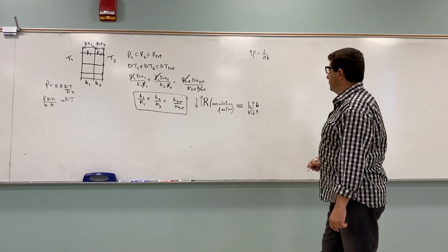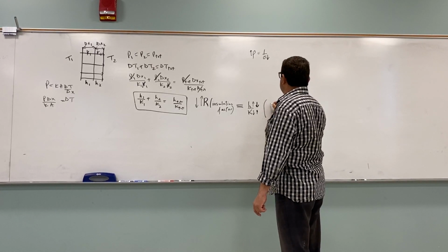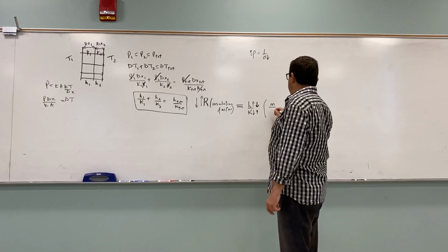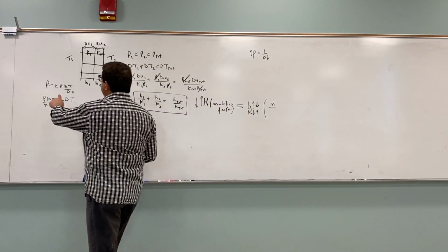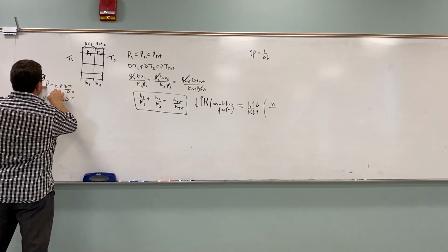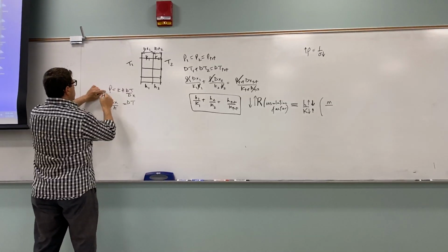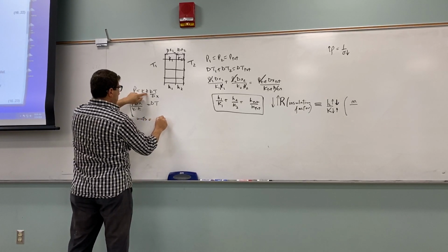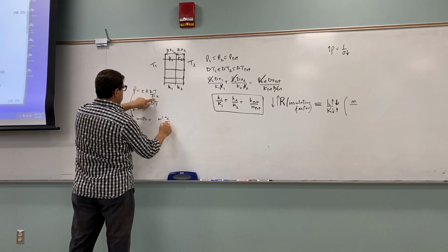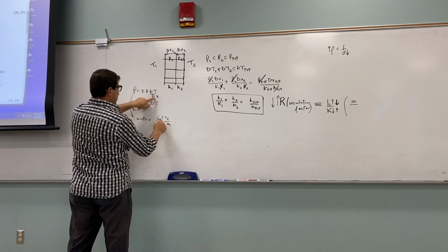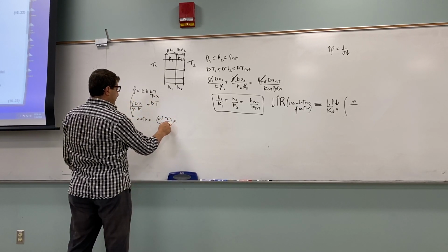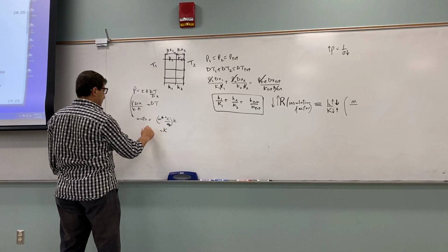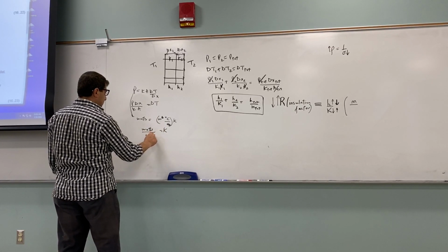So the units of the insulation factor will be meters over the units of the conductivity, which was what? Remember the units of K were, so if you always forget, you can go back to the equation. You can say this is watts, this is meters squared, this is Celsius over meter. And then the units of the K, one of the meters cancels. So K must be watts per meter Celsius.